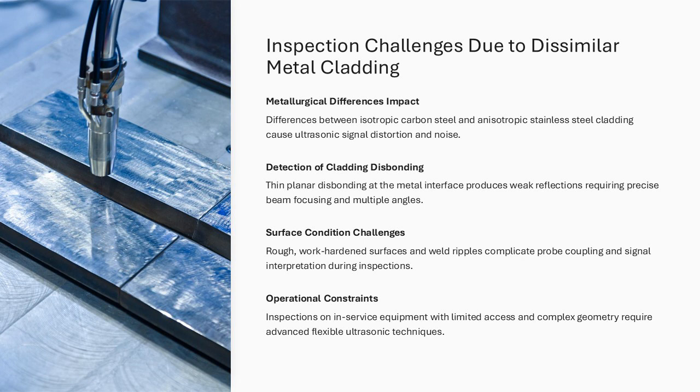These factors necessitate advanced, flexible inspection techniques that can adapt to geometry while maintaining accuracy. Understanding these challenges is essential for selecting appropriate NDT methods and designing procedures that provide reliable, repeatable results suitable for engineering decision-making. Conceptual image representing ultrasonic beam distortion and scattering when propagating through anisotropic stainless steel cladding.